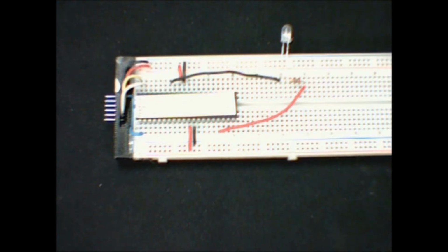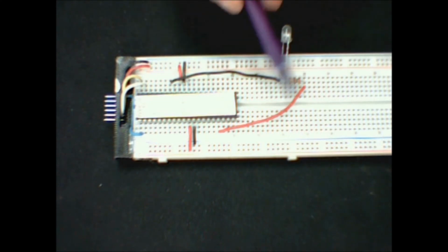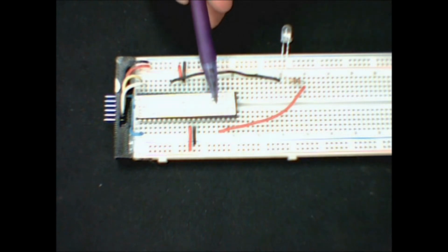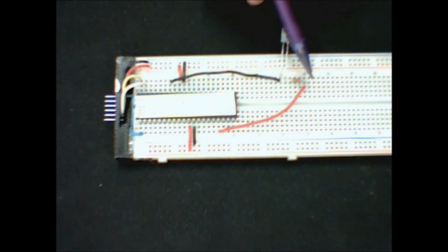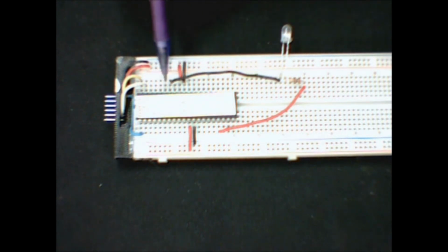So this is the setup that you use to explore what the program PWM.C does. You've got a 2-way LED, which I've left hanging off the side of the board just so you can see it a little better. And you should have a buffer resistor so that you don't burn out your LED and you don't pull so much current through your chip that you burn it out. So where do these wires hook up? Remember, you've got a square wave program to come out of pin 17. So that leads into my circuit. It goes through the resistor, then through the LED, and then it goes on to either pin RB0 or RB1.